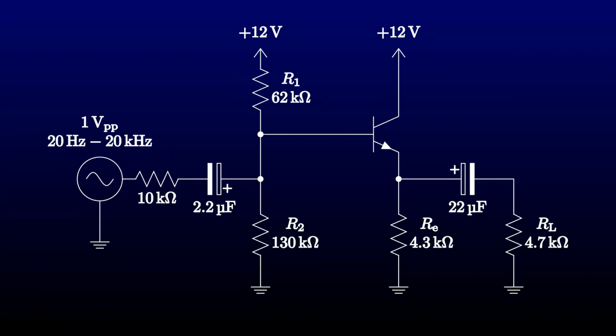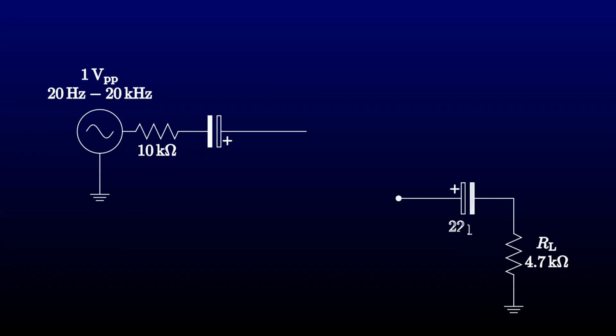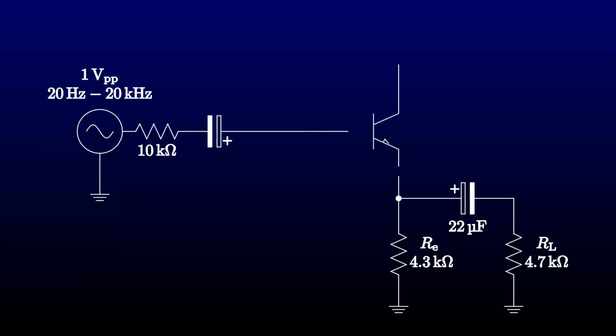It turns out that there is a way, and it's quite clever. It's not too different from what we've already seen. We are still faced with the same relatively high impedance source. We'll still couple that source to the base of the transistor with a capacitor. We'll fill in its value shortly. The load and the output coupling capacitor are the same. The pull-down resistor still draws the same quiescent current, and the transistor is still connected as a follower. The bias network is slightly different.